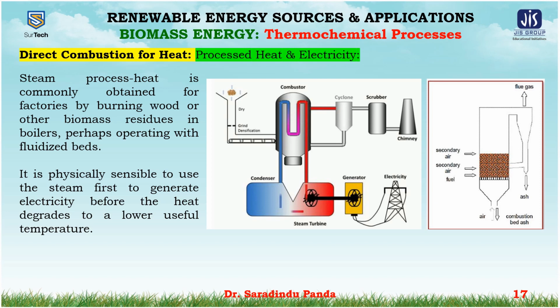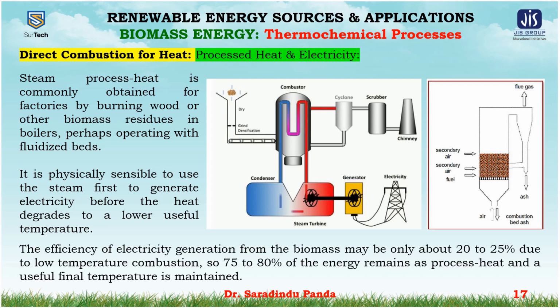The design of a fluidized bed reactor increases heat transfer and allows for operating temperatures below 950 degrees centigrade, reducing nitrogen oxide emissions. A fluidized bed combustor can handle high ash fuels, agricultural residues, and sewage sludge.